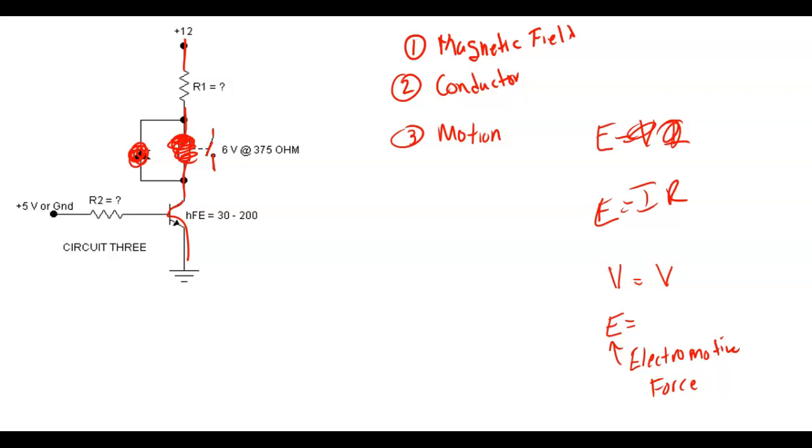And I'm going to disconnect the power to the circuit, which is what I do when I turn off my relay. Here's the power to the circuit. Did y'all see the light bulb flash? That means when I charge this up and discharge this inductor, which is the relay coil, it put out well over 100 volts, even though I'm only charging it up to what? Less than 4 volts.